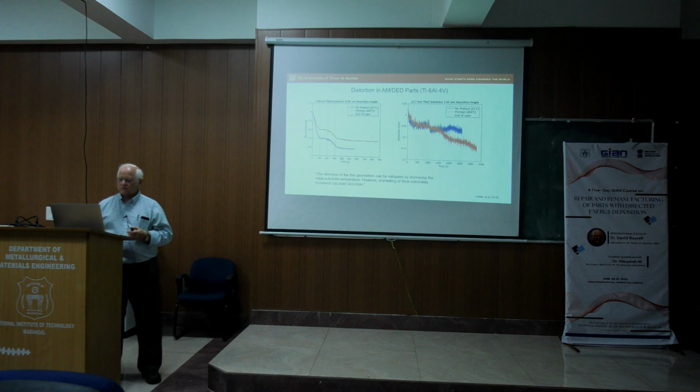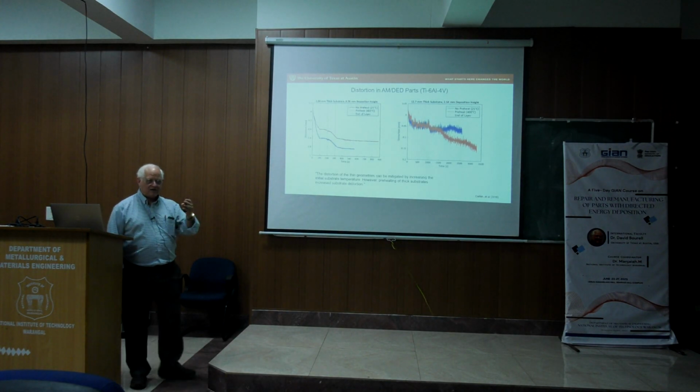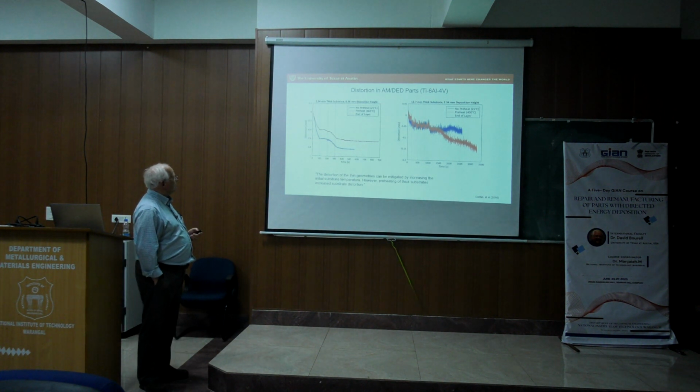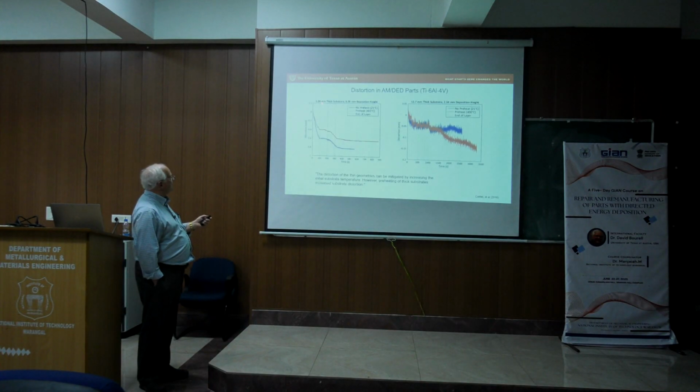All right, this shows the case for this esoteric silicon carbide, which has many post-processing steps. Let's move on and see how it works with distortion in directed energy deposition. Again, this is Tyson's work, and what's seen here is the build time and the distortion that occurs. This is for a 1-inch thick, 2.5 or 1/10 of an inch thick substrate with a 0.76 millimeter deposition height. So we're doing big distortion measurements.